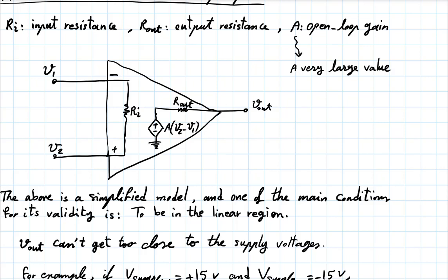You don't want it to influence what's going on before you have connected something to it. So you want a high resistance here so that the current that's drawn through this is little. And the circuit, whatever you're connecting this to, is not going to change its behavior.